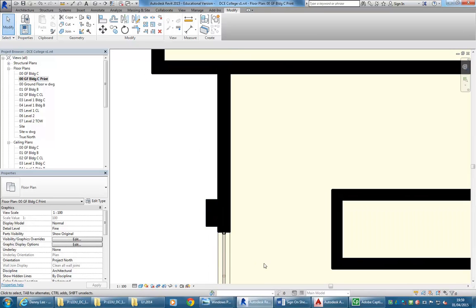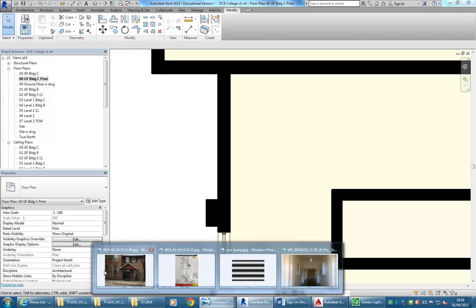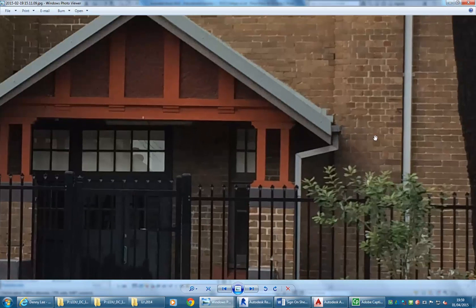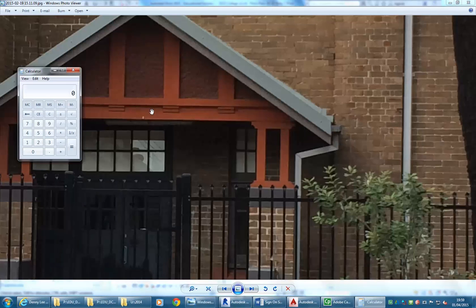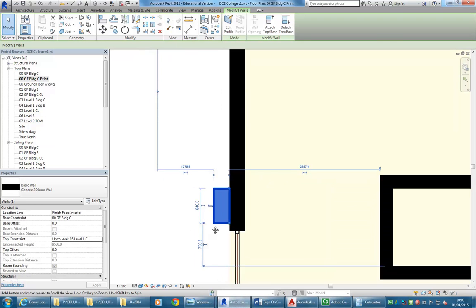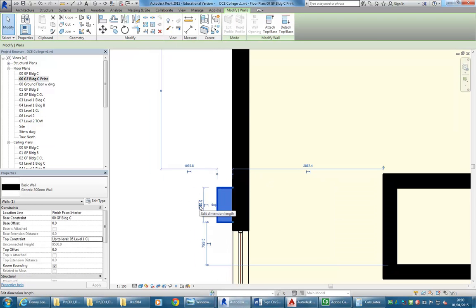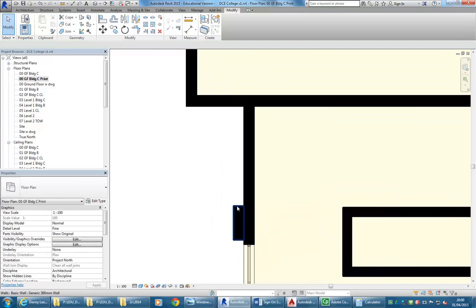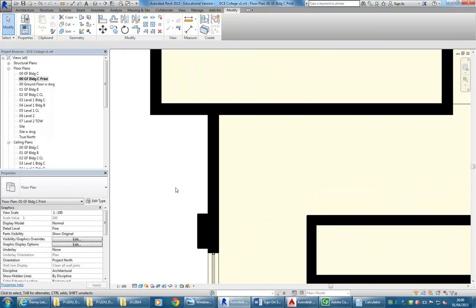So that gives me the set out for my pier there, but I could even look at the photo and see, well, we've got, 1, 2, 3, 4 exactly measured across. And it's late, so I will not multiply in my head. 4 by 240, 960. Should have been able to work that out, but anyhow. So that's what it is. Whether we want to make it that, yeah, may as well, I suppose. So that then helps me to work out the area my roof needs to go.